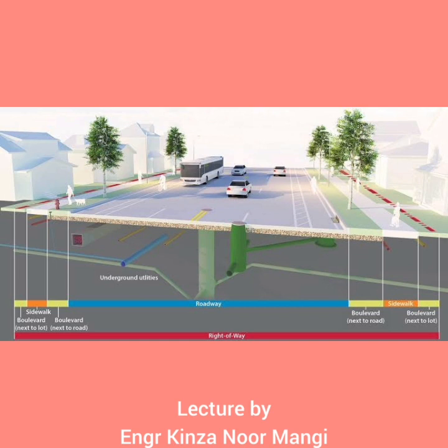Following are the influencing factors for right of way: width of the formation, embankment depth and cutting depth, side slope of embankment or cutting, drainage system, side distance considerations, future widening and service roads.